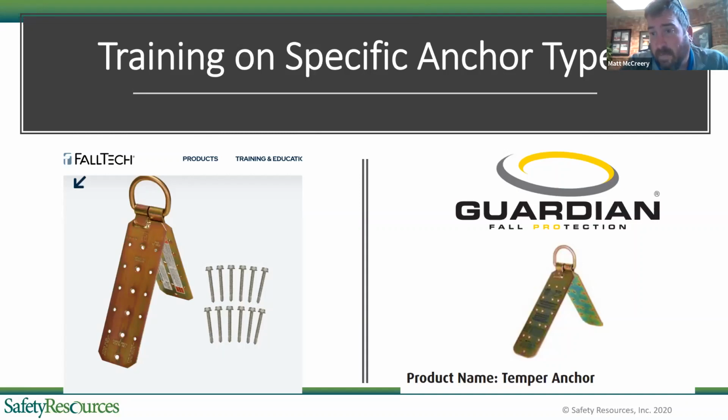And we've had to really think about how in the hell we're going to tie these folks off and get them up to that level. We've developed systems where we've run ropes up and over a domed roof in order to be able to implement correct fall protection.